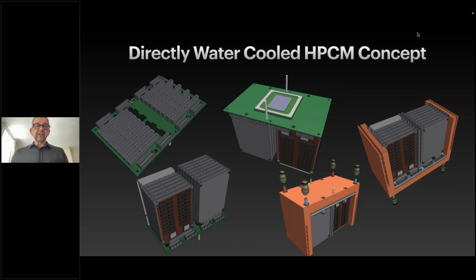And so you can see in the top left that there are 16 EDSFF connectors, which is obviously the standard that's becoming very popular now for SSDs and CXL.mem, and the NIC 3.0 standard also uses these same connectors.